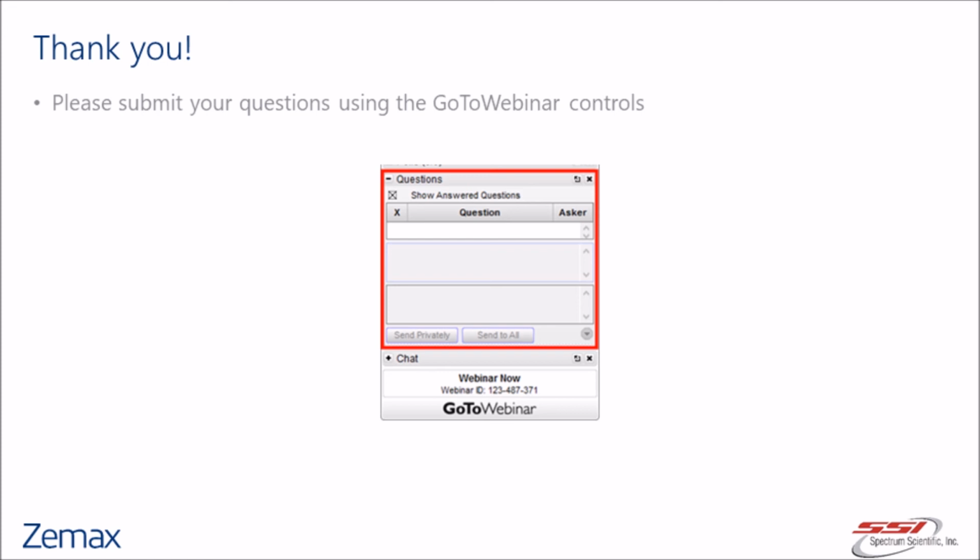One of the beauties of the replication process is that you can have mechanical interfaces that aren't directly on the optical surface, but the optical surface is aligned relative to those. You can imagine having a right angle post with a plate and some pins and a flat, and have the optical surface orthogonal to that and aligned very precisely. A really simple integration of complex systems. I see. And because you've got the master to measure, you can locate those very precisely with respect to, say, the vertex of the optical surface. Correct.